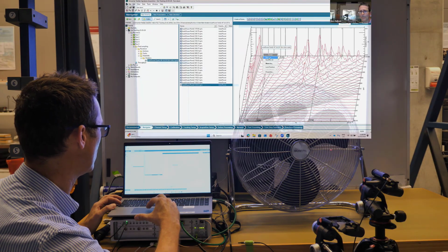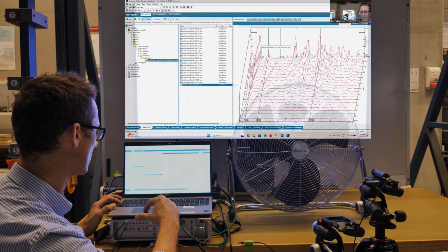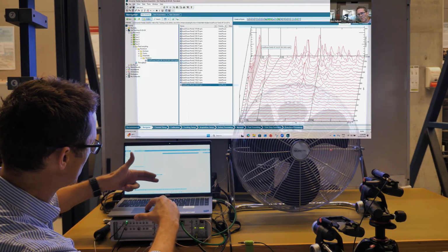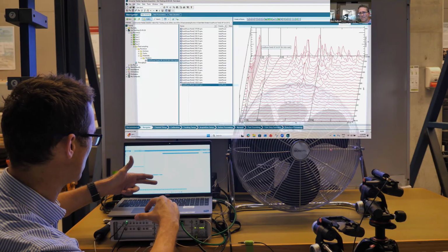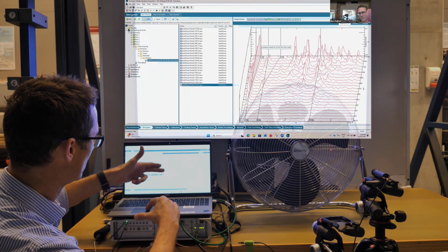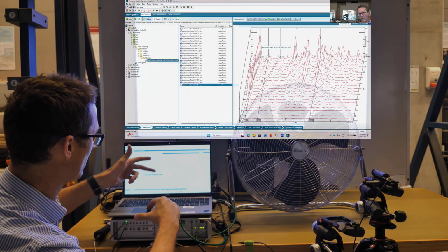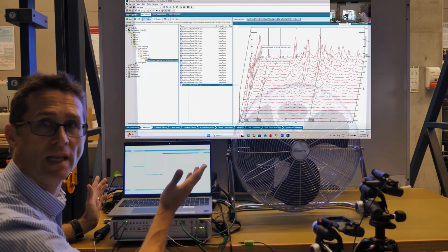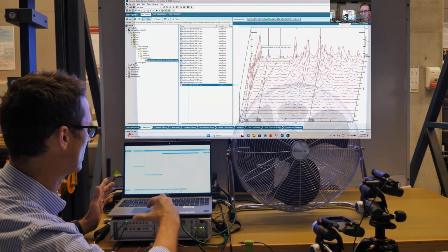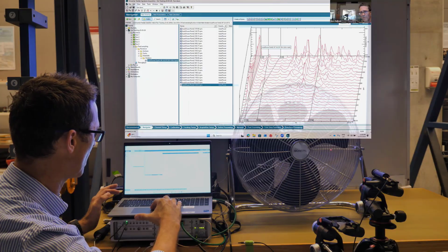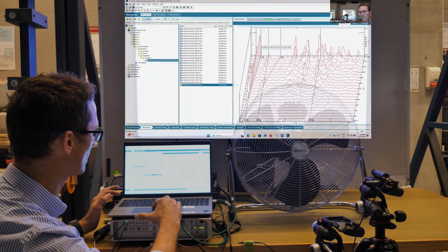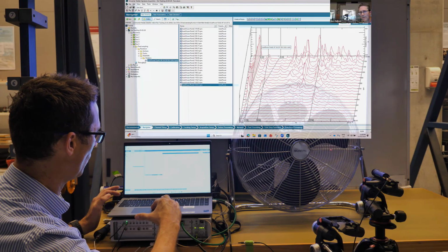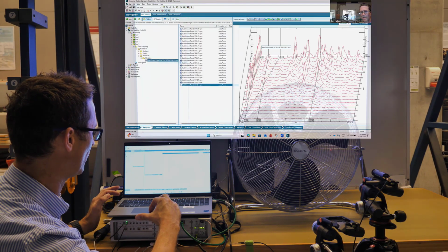I'm just going to remove that other harmonic cursor because it does make things a little bit cluttered. 11, 38.3, 153 approximately. And what's really interesting in the way that these data are presented is that, as you can see, there's lots of extra vibration along the 1 times order. That's because there's a lot of imbalance in this system, so there's always lots of vibration at 1 times. But when it coincides with this 11 hertz structural resonance, we get super high peaks. So those peaks in this region here are where the first order coincides with the 11 hertz resonant frequency.